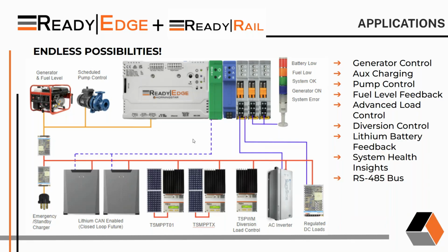In our case, you can just buy an MPPT for each tracker that you need, and that's a much more configurable and expandable and efficient way to build a large system, because you don't end up buying more than you need, and it's easy to expand in the future. So in this case, we have 2 TriStar MPPTs here, but maybe you have 4 or 8 or more.